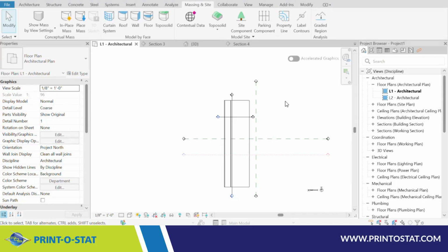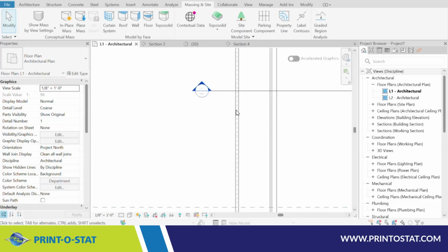In this video, I want to show you a slick little idea of how to manipulate your topo points to get them where you like them. This is just going to be a one elevation concrete sidewalk next to a building. Here's the building wall, the sidewalk, the curb line. That's a section line right there, but the curb line here, and topo up against the curb.